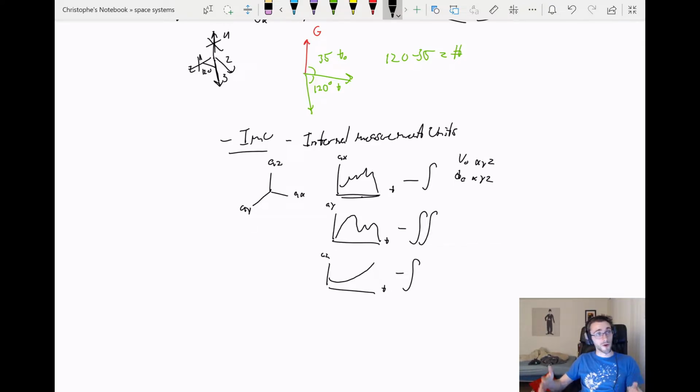and from that, given that you know where you were, the amount of time that's passed, and your different acceleration curves in the x, y, and z, you can figure out how fast you're moving with respect to time in the x, y, and z, and how far you went in the X, Y, and Z. So that's how IMUs are used to measure translational motion of a space vehicle. But you can also use them.